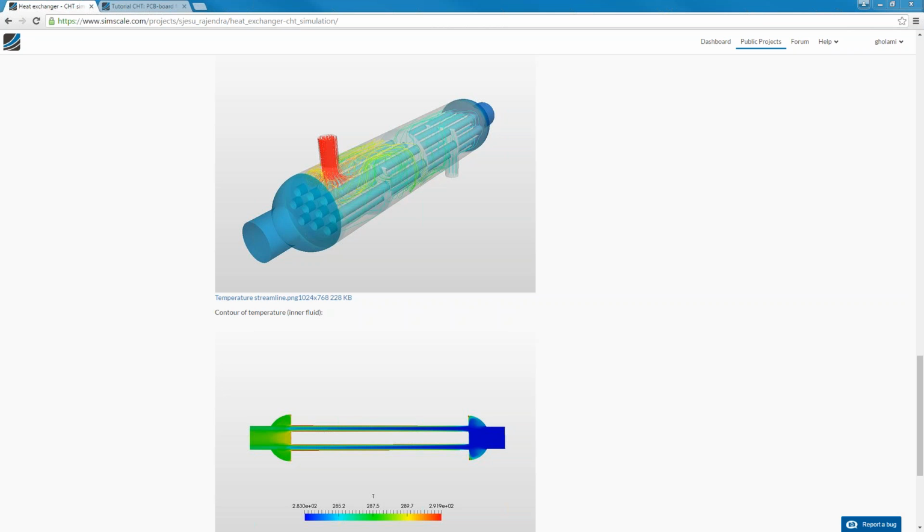We have a question about turbulence models. What kind of turbulence model is recommended for a steady state turbulent CHT simulation? I would say it depends on your application. So we have both RANS and LES models. You really have to see what kind of phenomena you are dealing with. Are you dealing with a highly turbulent flow with transient effects? If that is the case, you have to go with an LES simulation. It's more expensive, of course, but up to a certain scale, it resolves the turbulent behavior. If the level of turbulence is not that high, you could use the RANS models, which we have actually: K omega SST and K epsilon. These two are already offered.